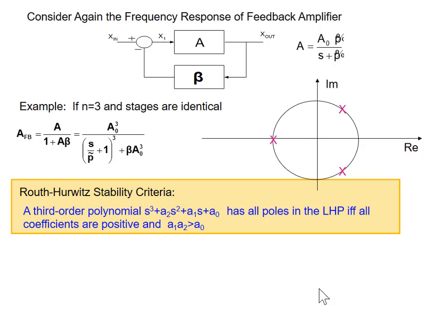So let's look at how we might be able to take a denominator polynomial and determine if an amplifier is unstable, because it's not a lot of fun to find the roots of a polynomial. If we have a third order polynomial in general, I was able to solve this one, but I can write down third order polynomials pretty easily that you can't easily solve. All I have to do is let those 3 roots be different. If you want to write down the expression for those 3 roots, it'll be 2 pages in 6-point font for each of them. Are you with me? Okay.